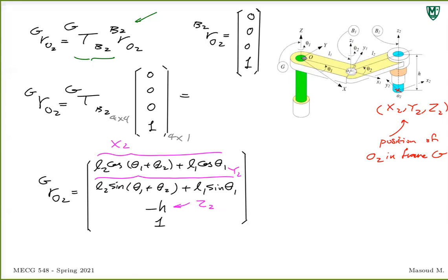Let's say it's on a table, you want to reach out, and your arm is your origin. You want to reach out to a specific point, pick something, and place it at another point. As long as you know those coordinates, you can play around with theta 1, theta 2 and H to get there and put it where you want. You have a full understanding of the kinematics of the tip point. All right, I'm just going to stop here.